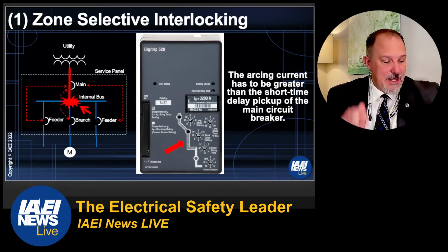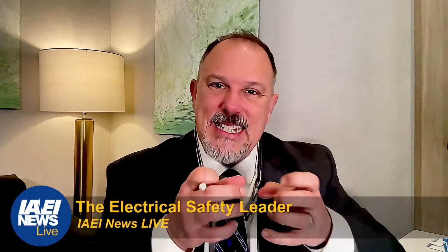And think, built into each circuit breaker are sensors, the CTs that you would be putting in externally. Now they're built into the circuit breaker. Even the small molded case circuit breakers have sensors, those CTs. So you're not field installing CTs. And the relay, it's in there. You don't have to put a separate relay. So you've got a microprocessor that is probably more powerful than what put us on the moon inside of every one of these circuit breakers.